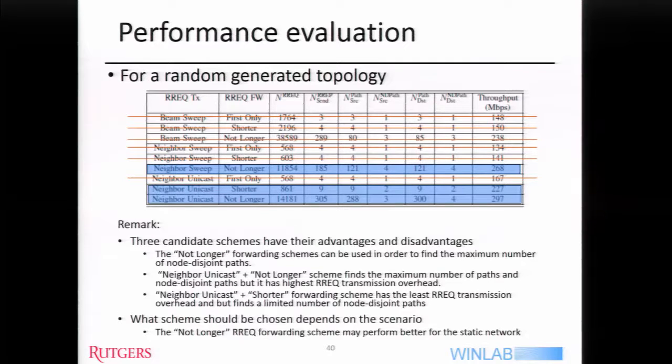And to even further remove myself from the ad hoc community, can you summarize at a very, very high level: because we have directivity of the antennas, is there something fundamentally different from the multi-hop ad hoc protocols that people have been studying over a long time, to make things work in these directive channels? And what would that be? Yeah, the first thing is the high spatial reuse. Okay, right. Yeah, that is one. A good protocol should give you much higher capacity because the beams are giving you that.